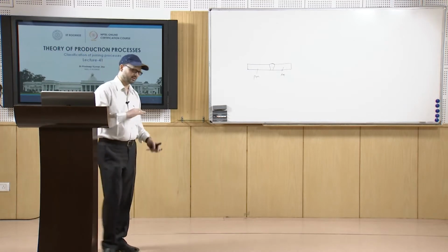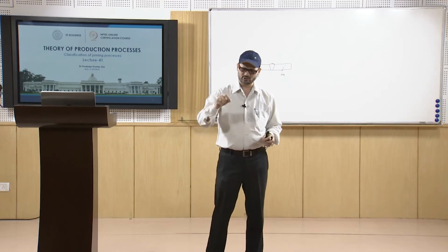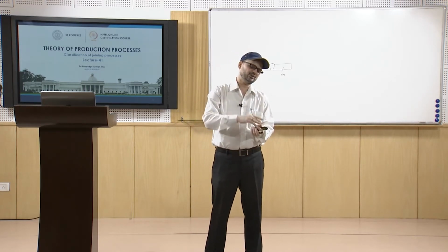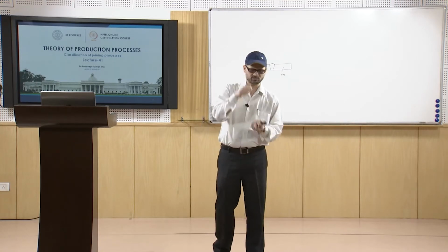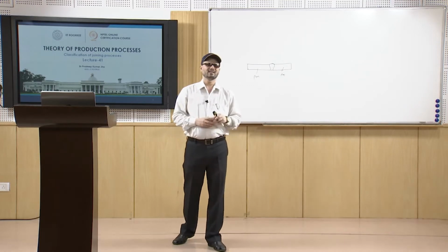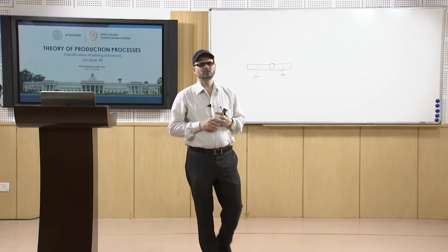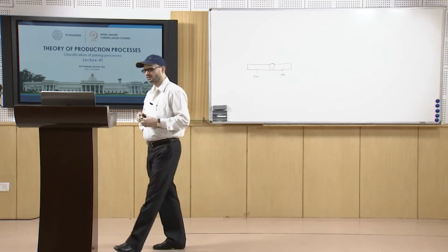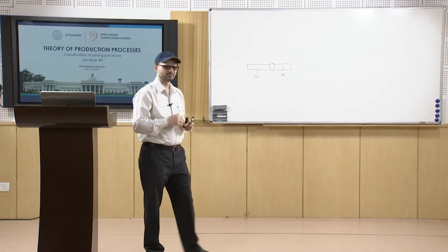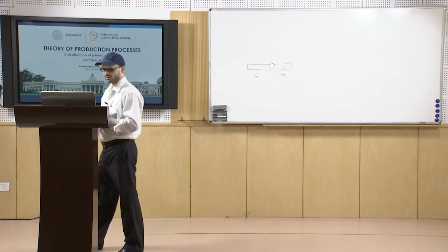Normally in the case of automobiles you have sheets, and at the points where you have to do the spotting, two electrodes come from opposite ends with the sheet between them. They touch at the spot, and because of the resistance heat is generated, and then the joining takes place. This way, using resistance, the welding takes place either on a spot or on a seam, known as resistance spot welding or resistance seam welding.